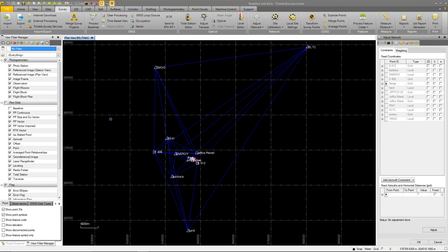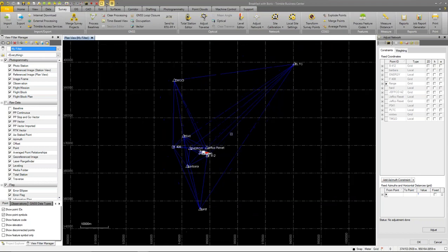It depends on the situation. In this case, I could actually delete that data sheet and go in and create a coordinate value under B412 that's purely a vertical-only coordinate, doesn't have any other coordinates on it, and use that for my control later, or my constraint later, and that would get rid of that message. In this case, I can choose to ignore it, and it doesn't bother me that it's there. The choice is yours how you want to address that kind of stuff.